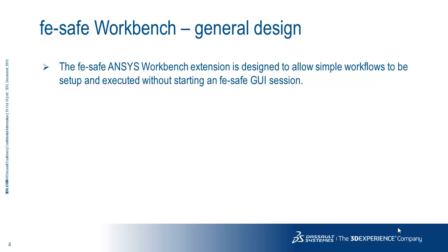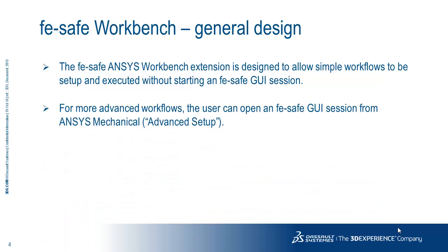So the main objective of this FE-SAFE ANSYS Workbench extension is to allow these simple workflows to be set up and executed without starting any FE-SAFE GUI session. So that is the main objective. But right now it is only possible to do a simple workflow. If there is a complicated workflow, then directly from ANSYS Mechanical you can open the FE-SAFE GUI using advanced setup.